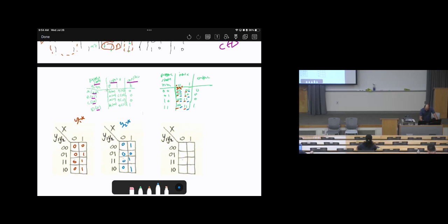Then, regarding the outputs here, it can be for both columns. So 0, 0, 0, 1, 0, 0, 0, 1. That's why we prefer to use this Karnaugh map, so you can copy this from the original Moore model, or it can be applied for the Mealy model the same way. Okay? So this is here for Z.